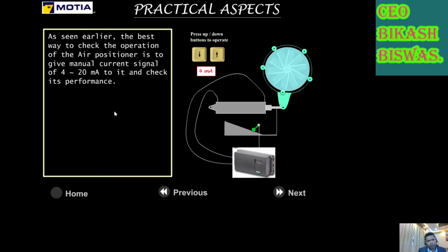So how will we know? Any problem that happens on board, just follow the basics. You have to divide this problem into parts, and stepwise thinking is required to take a wise decision. So suppose there is a problem. Now I want to identify, is this problem coming from the CPAT IP positioner? I know that the 4 to 20 milliamp signal is coming from the combustion controller CPU.